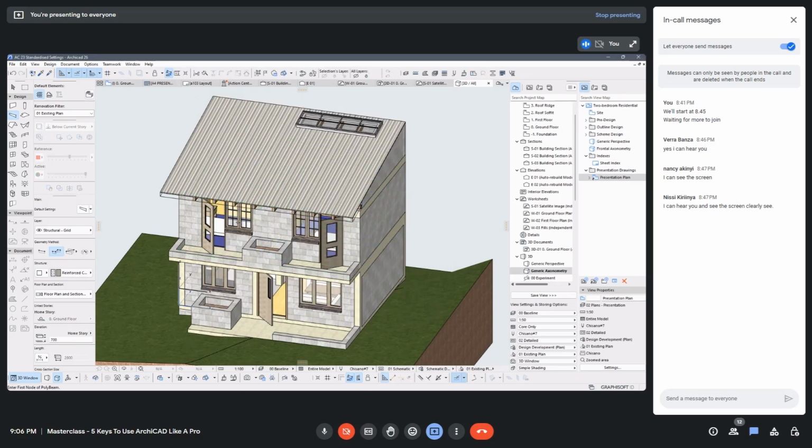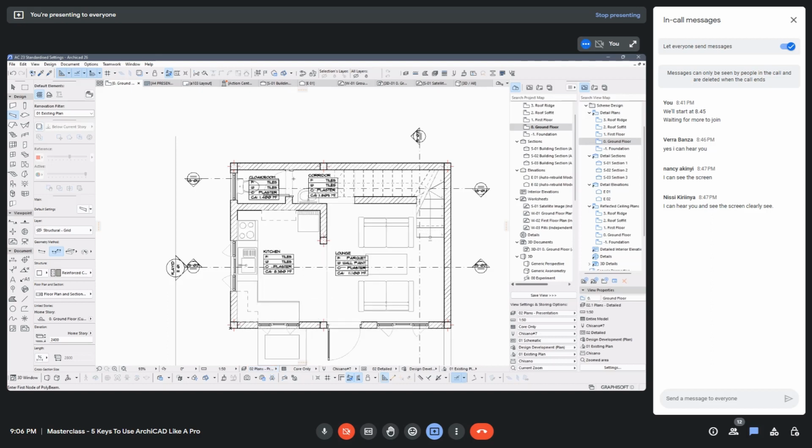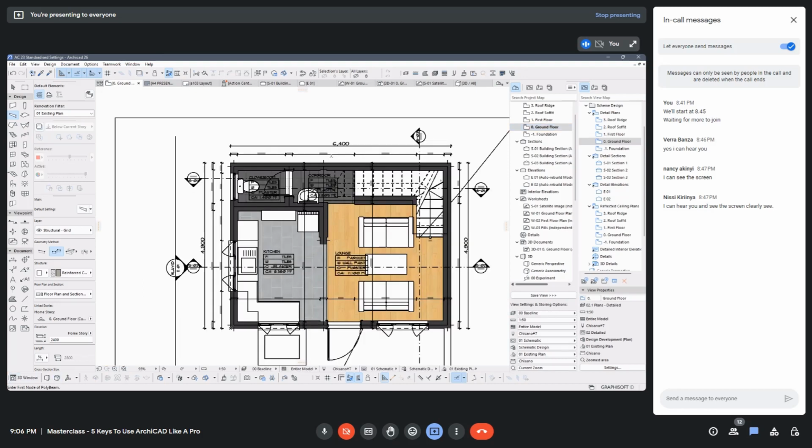But say I'd want only specific walls to act as load bearing elements. So let me just select a few walls. Let me select only the exterior ones. Or let me just decide that all my walls on ground floor aren't load bearing.